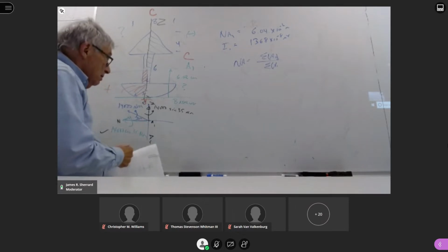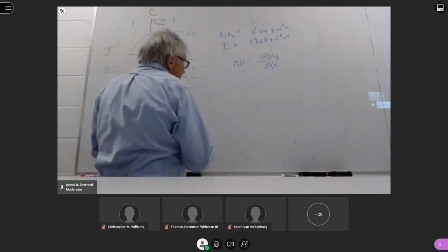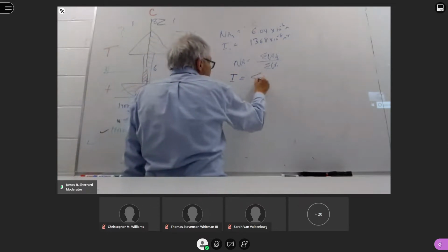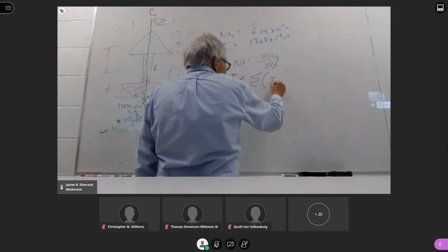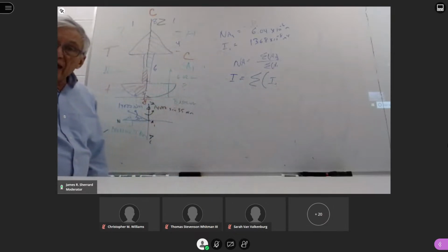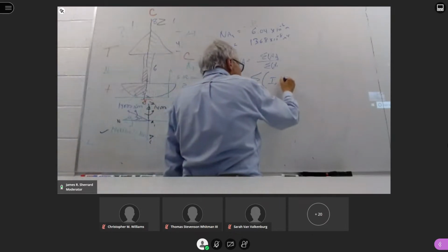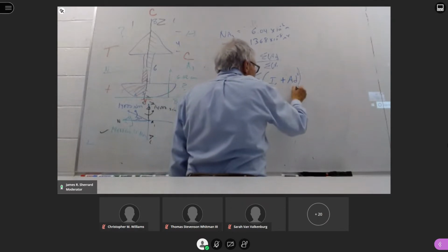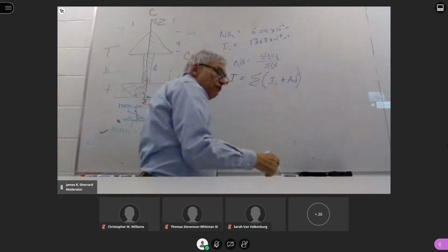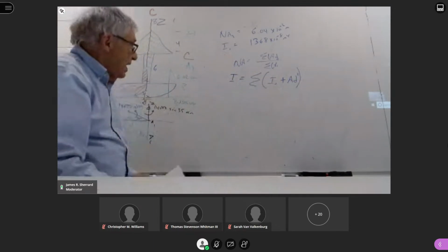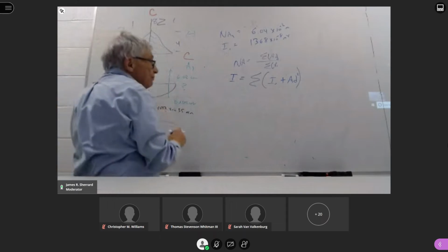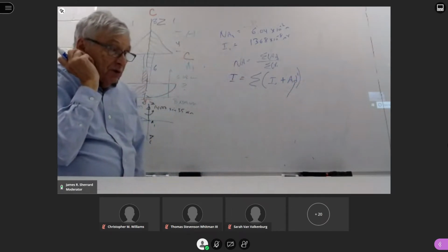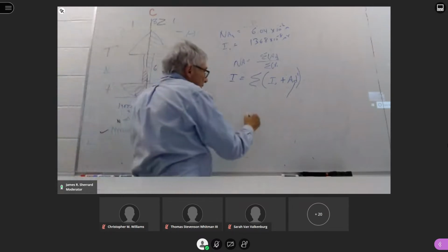When we did the rectangular moment of inertia, we know the rectangular moment of inertia is equal to the sum of the individual rectangular moment of inertia for that shape plus the area of that shape times d squared. We're going to have to do this calculation for however many number of segments we have. So again, 1, 2, 3. And this d squared again, because in looking at some of your quizzes, you're missing the point here.